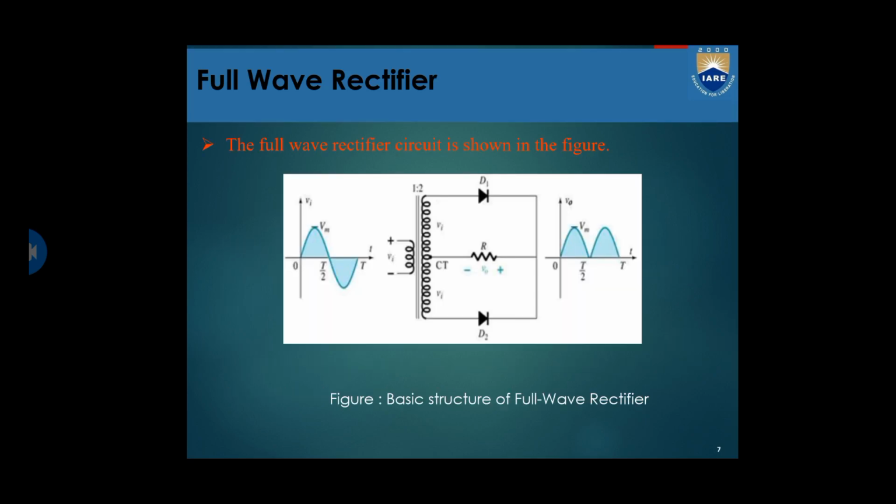This is a full wave rectifier. You can see the pictorial representation of the full wave rectifier in the circuit below. The center tap is connected to one end of the load resistor. Both the half cycles, positive and negative, are converted into a single DC fluctuating cycle.